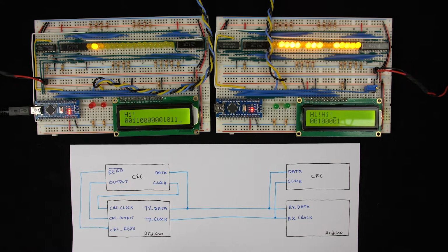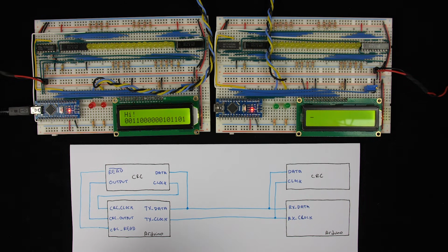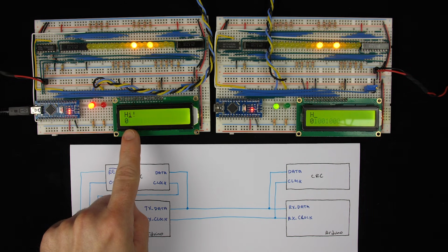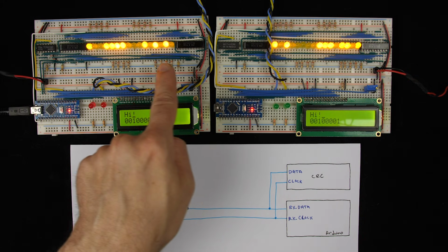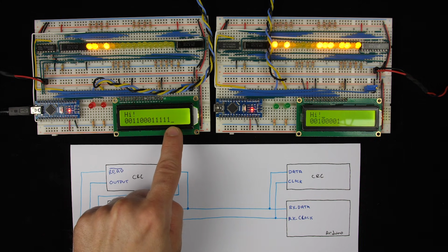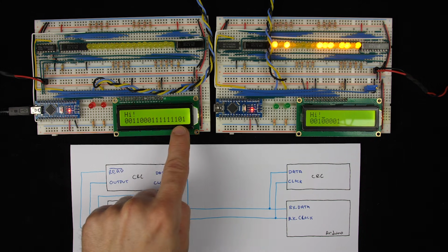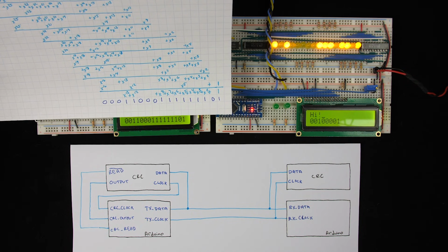And you can see it's reading something in there, but let's go ahead and reset everything. And we'll run this again. So now it's going to send the H, it's going to send the I, it's going to send the exclamation, it's going to push 16 zeros into the CRC, and then it's going to read the contents of the CRC out. And so there we go. That is our CRC, and we can look here, and in fact that is the correct CRC.